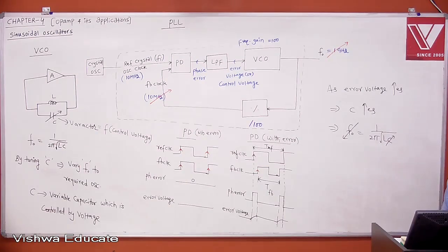For a VCO, input is voltage, output is frequency. That is the gain. People call it KVCO, the change in output frequency with respect to the change in input voltage. That will determine how much range it can correct. But this is the block diagram to understand, to start with. It has negative feedback for frequencies. Okay.